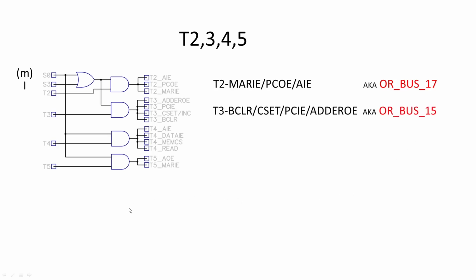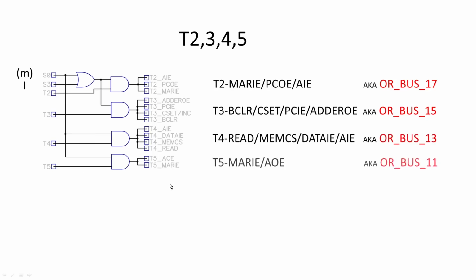Now, when we're doing the memory direct addressing mode, we go into T4s and T5s for that. We only need memory addressing mode for the source feeding into these. If we're on T4, we turn these signals on, and when we get to T5, we're going to turn those signals on, and we can combine them all onto those four there. So that's the addressing mode for the first source.